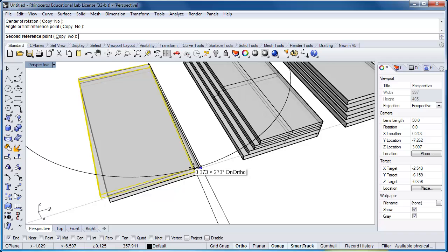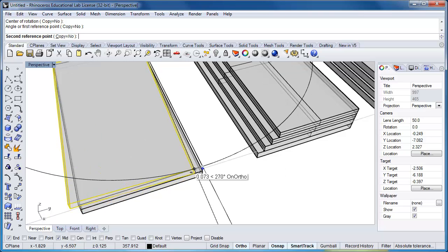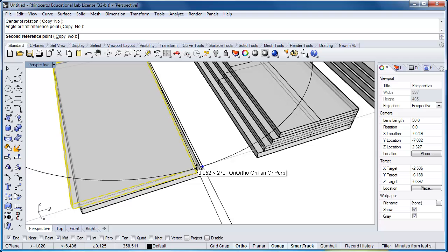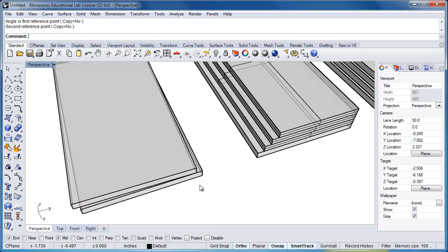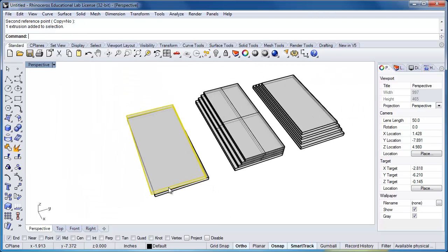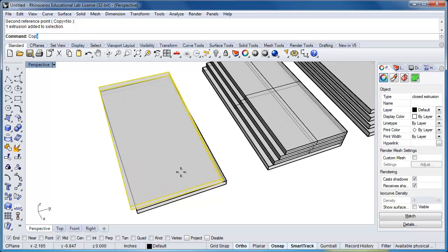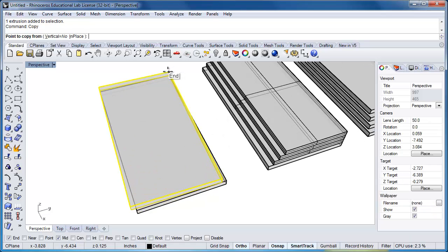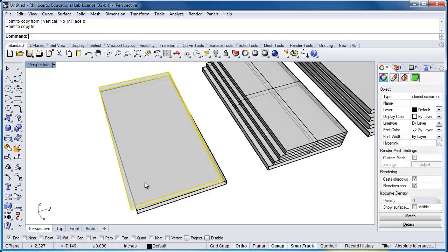And if you wanted to, you could give yourself a construction line so that you set exactly what the length is, what the distance is along that curve. And click. And then you can keep doing the same thing. Once you've set your rotation distance one time, you should be able to keep using that same rotation distance over and over again. So let me show you.